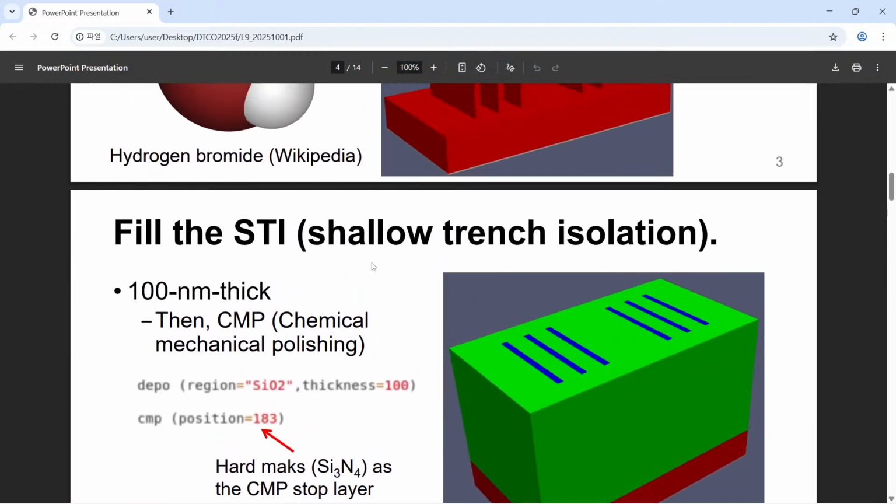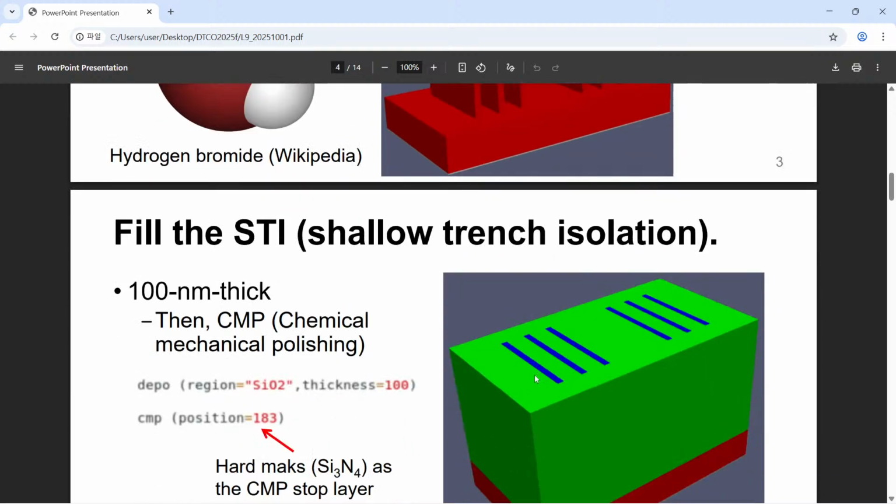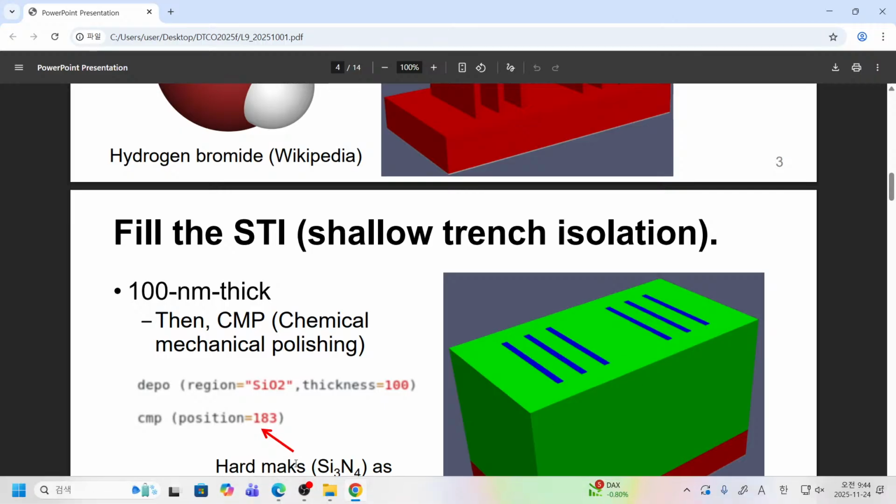Although it's not exactly a layout, you can see that this part is aligned to our NMOSFET part, and this part is aligned to our PMOSFET part, and the dummy gate runs vertically across the fins, and here we have some space. Usually we can place something in this unused space to make a connection to the external world. So let me just come back.